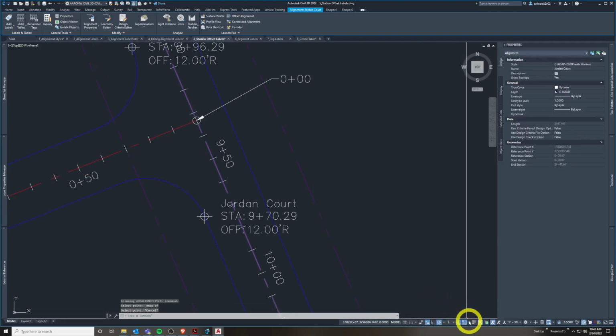That's a little different. If you go to your tool tray down here, these are your running object snaps. Critical to AutoCAD and Civil 3D, but AutoCAD Learning 101. These you turn on and off. So when they're turned on, this endpoint snap stays on every time I want to snap to something with endpoints. Depending on what you want to snap to, the center of a block, a node of a point, a midpoint of any line feature, a center of any arc or circle, you can turn these on and off and they will stay on, running.